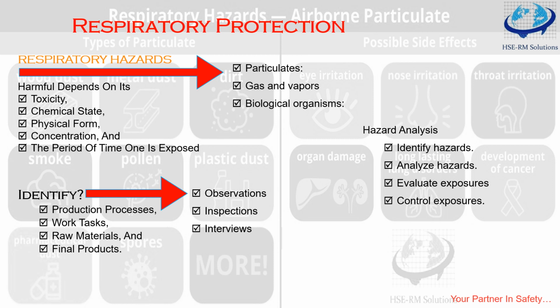Now, when we seek information, where will you get the information on permissible exposure limits for a specific air contaminant? You can refer to OSHA standard 1910.1000: Table Z1, limits for air contaminants; Table Z2, toxic and hazardous substances; and Table Z3, mineral dust.